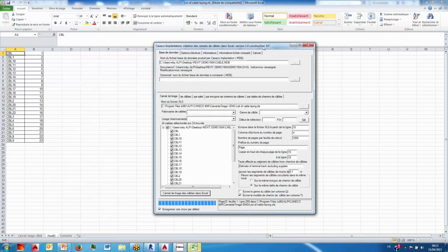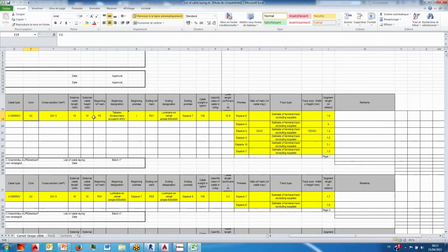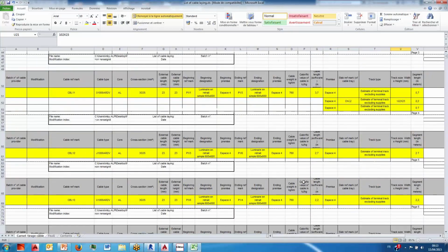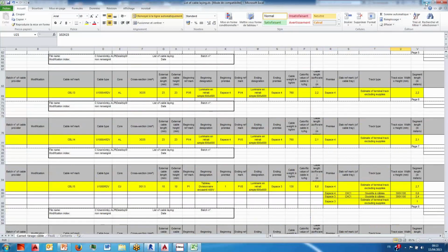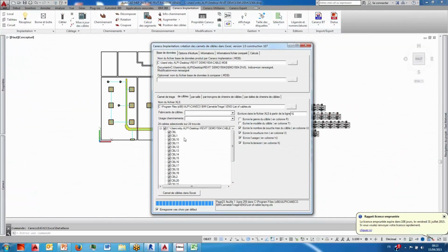So you see, it just generates a cable, an Excel file that you can see here. You have the list of cable, the kind of cable here. Let's take a zoom on it. It tells you exactly which kind of distribution, the circuit, where the cable chain, which space, which kind of the cable tray. So it go in details to tell you what happened on the cable trays.